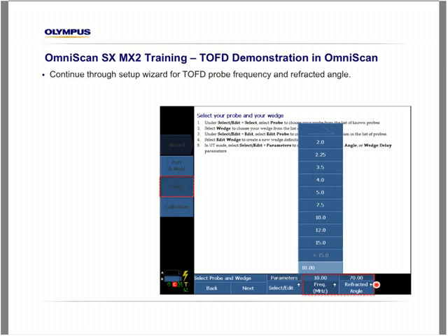The refracted angle only exists in the software for a report or recording of what angle was used for procedure compliance. The refracted angle plays no part in the algorithms or calculations for depth and height. It's only a recorded part. The wizard also allows, under the edit button here, to enter the specific wedge and probe model from the database, but it's not necessary for the acoustic performance.